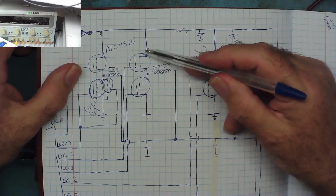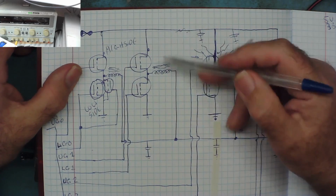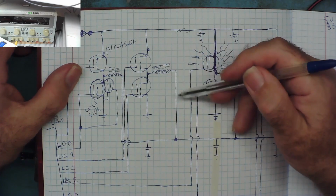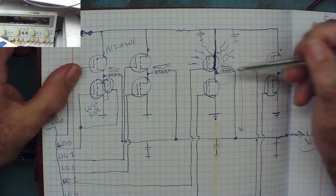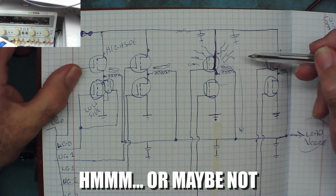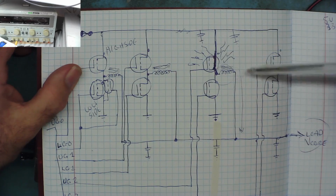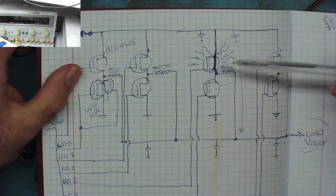this end of the coil is effectively open circuit because both these MOSFETs are off. And I'm expecting to see some sort of spike or pulse here, a ringing effect on the oscilloscope on all the good phases and not on the bad. I have no idea if this is going to work, but the theory seems good. So let's try it and see if we can determine which phase has a short circuit high side MOSFET by ring testing the coil.